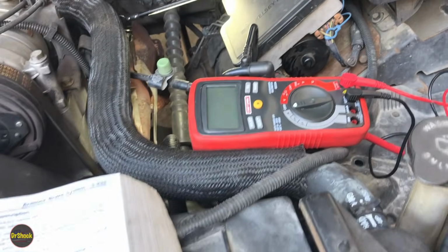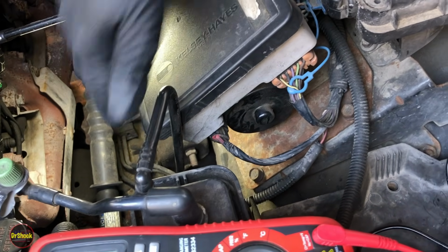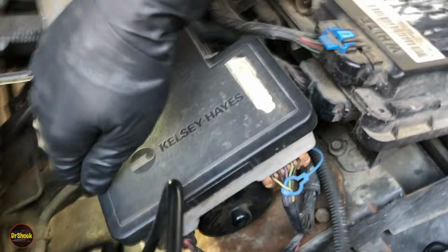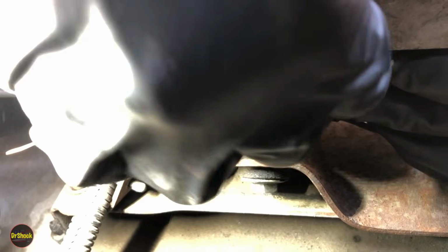So the first test is this connector on the back here, and we're going to have to see how we can get the camera down in here so that you guys can see that. All right, guys, for this first test, we're after this connector right here, which is from the BPMV's pump motor into the EBCM. So just got to get this little locking tab to come off blind here, because you guys can see it, but I can't. All right, there it is.